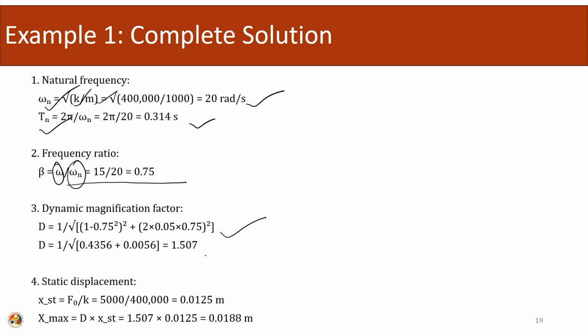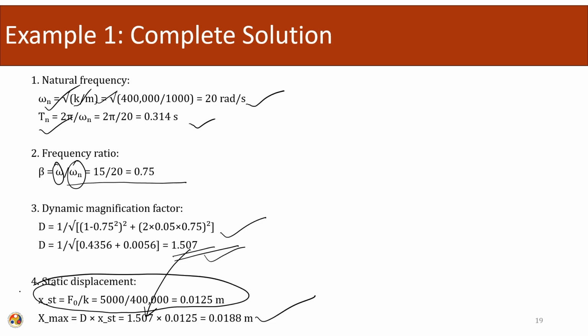Using the same equation we can calculate the dynamic magnification factor, and then we can calculate the maximum deflection. If we know the dynamic increase factor, and we have the knowledge for calculating the static response, then if we multiply both these things, we can directly calculate the maximum dynamic loading. We have calculated the dynamic increase factor, multiplied by U static and calculated the U dynamic.